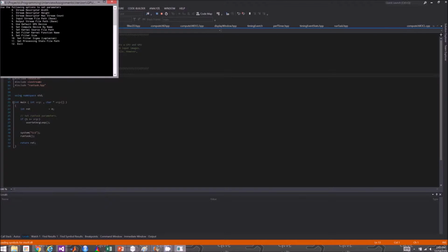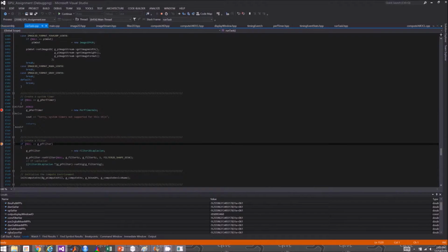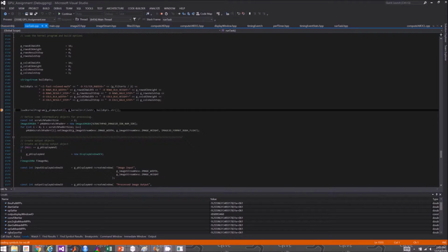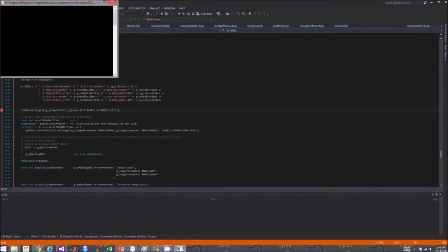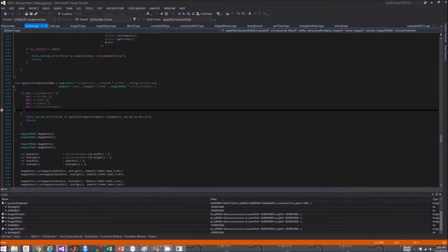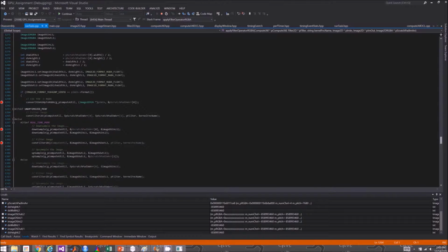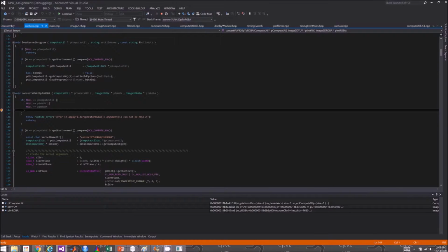Now we provide a live code walkthrough. Here we have the option to set parameters, and we enter our run task, in which we initialize our stream object, our perf timers, our filter, and load our kernel program. Stepping into the apply filter operation, we see this is our cascade of OpenCL kernels. First up is our convert YUV to RGB. We'll just step through this briefly.